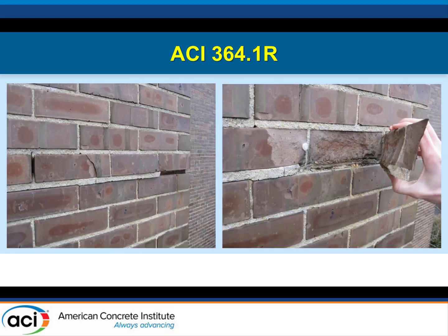The opposite was happening down at the bottom, where things were constrained. What you saw was a lot of brick fracturing that was occurring right in the relief angle lines. Now, the reason I mention this here is this is one of those symptoms that's easy to get misdiagnosed. A lot of people would look at this and they would see the corrosion of the relief angle, and they'll attribute this distress in the brick to rust jacking of the relief angle. It's not. Rust is really happening after the fact, after the moisture is getting in there and corroding the brick. The distress that's going on down here is driven by differential shortening. It's expansion of the brick and shortening of the concrete. Right?